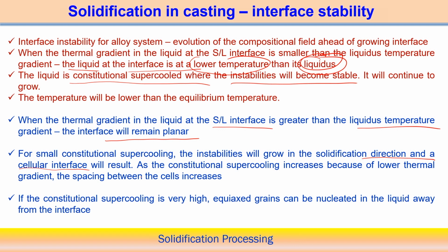We already saw that with more constitutional supercooling and a lower thermal gradient, the spacing between the cells also increases.